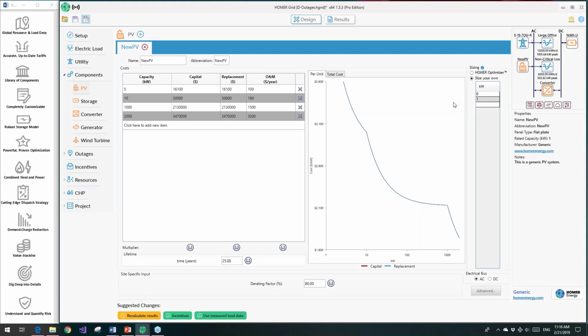And avoid doing unnecessary combinations of components or too many tariffs. Every time you add another tariff, it creates a whole other set of simulations which have to be run. So using the different components, sensitivity analyses and search space values sparingly will speed things up.